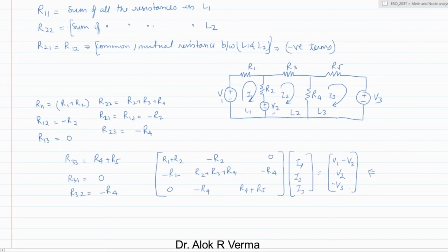So whenever you're trying to solve, first write the KVL equation, then form a matrix, and then practice it. That will be helpful in understanding the mesh analysis.